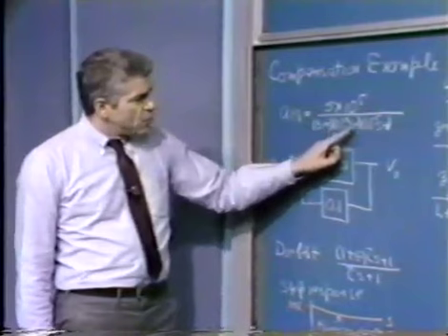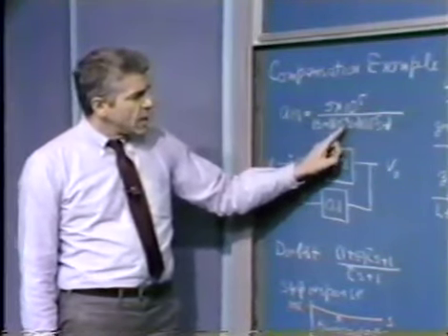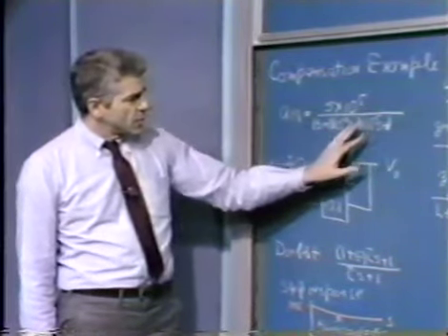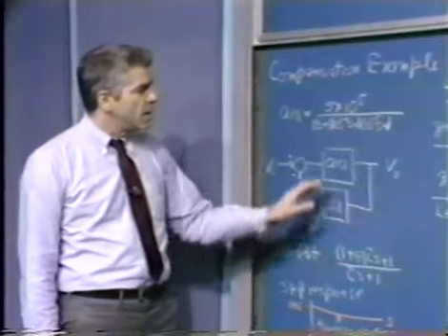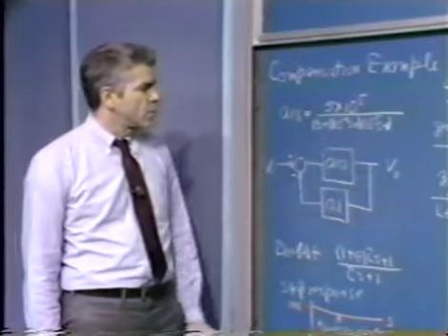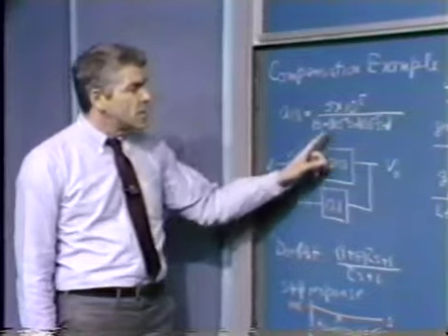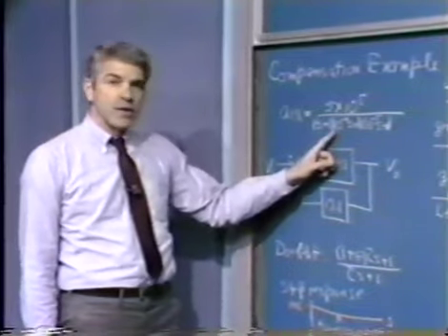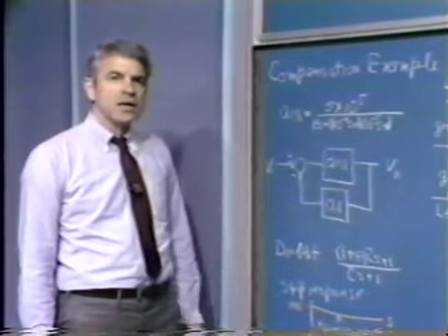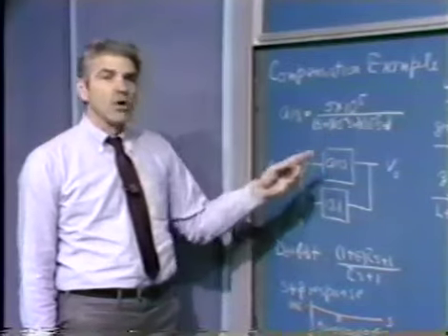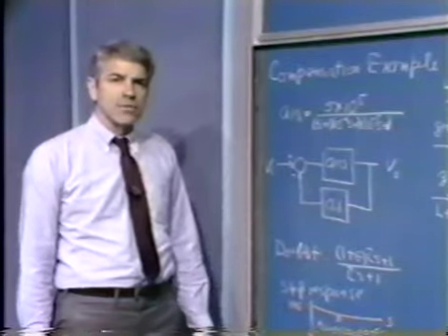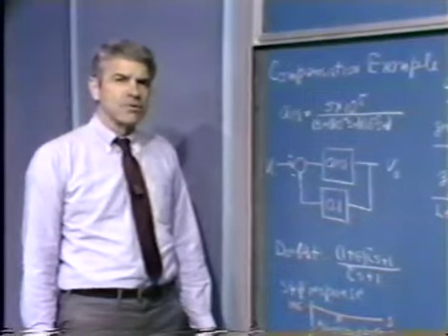The form where we have the high frequency additional poles coming in at somewhere on the order of 10 to the 4th radians per second is unrealistically slow for modern operational amplifiers. A more realistic value might be something on the order of 10 to the 7th radians per second for many of the common integrated circuit operational amplifiers.